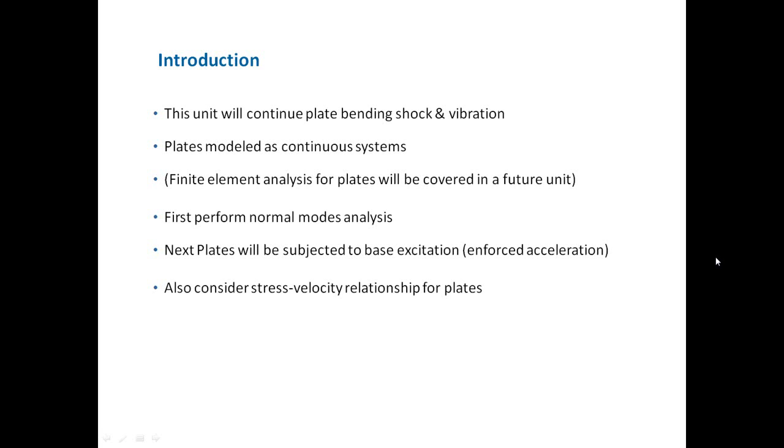We're first going to perform a modal analysis, or you could say a normal modes analysis, on these plates to find their natural frequencies, their mode shapes, and their participation factors. Then once we've done our modal analysis, we're going to subject these plates to base excitation, which is more accurately called enforced acceleration along the outer circumference or perimeter. And we're also going to take a brief look at the stress-velocity relationship for plates.